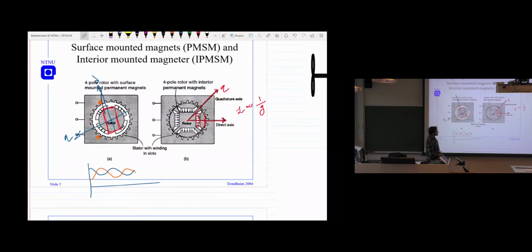So why do we focus on this PMSM-based machine? One advantage is that it doesn't have any coil here, any copper, so it improves the efficiency. Another thing is that when you have the copper coil, there's current flowing through it. This means it's producing losses, I square R. Since it doesn't have this coil there, the losses are much lower. That is the one advantage that we see.